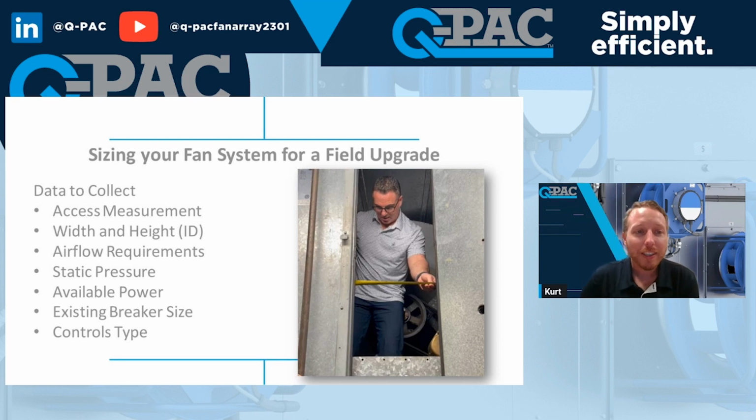So sizing your fan system for a field upgrade. So look, we have many different sizes of fans. Ideally, you want to choose a fan that can fit through the existing access door, right? But you also need to check the access of the entire building. So mechanical rooms can get weird, as we all know. There's a lot of random pipes and ductwork that you have to walk around. Walk the path all the way from the loading dock to the inside of the air handler.